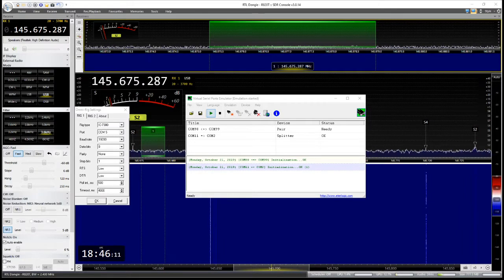Here we go. First thing you need to do, you're looking at this screen, get OmniRig installed. I have 2 rigs in here. You need to get the 857 into this, and this is for future. You don't need this running if you're just going to run Console with the satellite tracking program. But this is for the future if you decide to go to SAT PC 32. So I'm going to kind of lump this whole thing together.